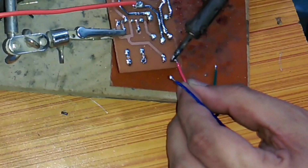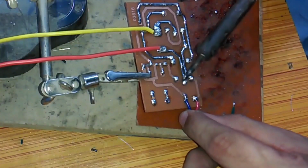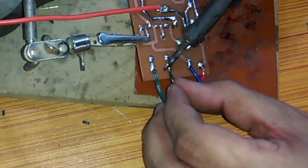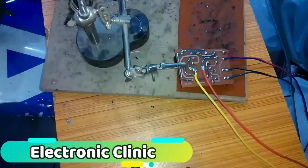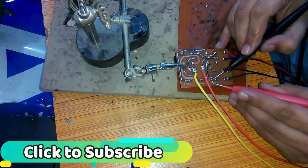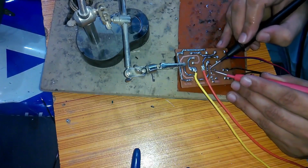And now these are supply wires. The red is a 12 volt wire and the blue is the ground wire. And now these two wires are connected with the 10K resistors, which later will be connected with pins 7 and 8 of the Arduino or ATmega328 microcontroller. So now let's check the short circuit and the continuity.